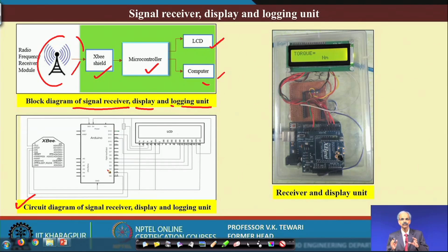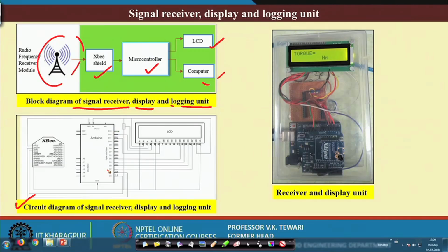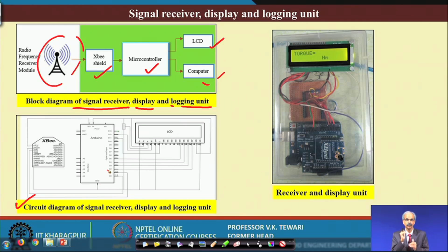Just to explain to you what instrumentation and knowledge has gone into developing this PTO torque sensor, and what has gone into the axial torque sensor. This is what we discussed today, and it is very essential to understand that such a high level of instrumentation is required for accurate measurement of power utilized by any implement when it is connected to the power source.